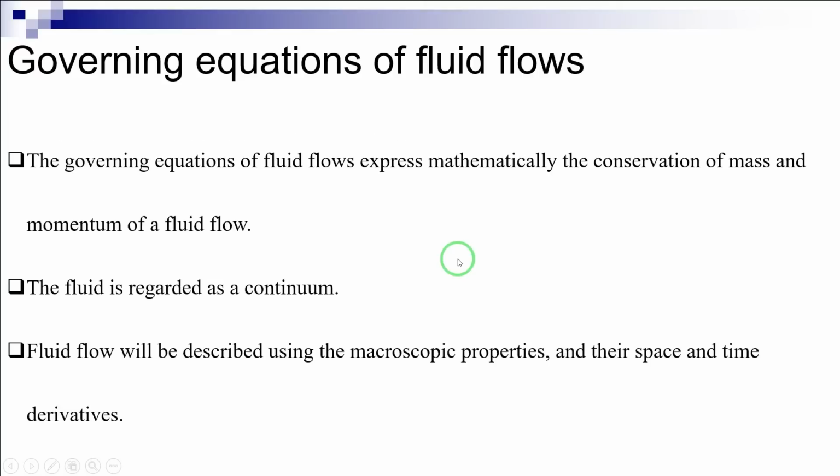Governing equations of fluid flows. The governing equations of fluid flows express mathematically the conservation of mass and momentum of a fluid flow. The fluid is regarded as a continuum. In other words, the fluid flow will be described using the macroscopic properties such as velocity, pressure, density, and temperature, and their space and time derivatives.